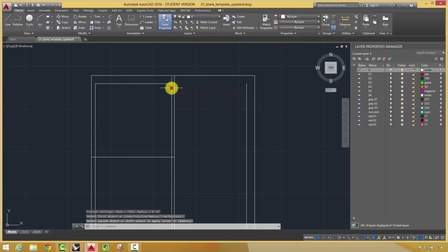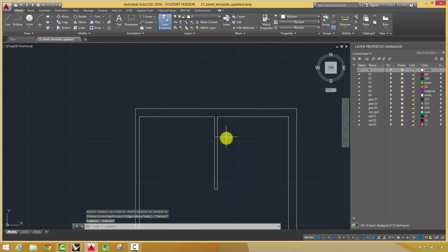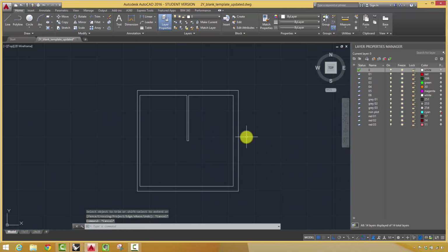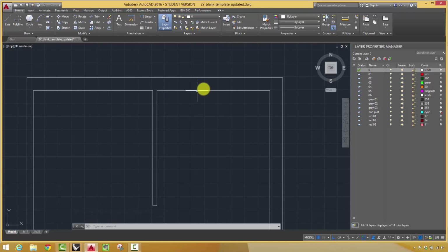actually, see, fillet doesn't always work because now I lose my line there. That's the way fillet works. So I actually do need to trim these. And once you get practice with trimming, that'll help. So you can see that the partition is not separated from the wall. The space, the wall, the thickness of it just kind of flows into it, right? There is not a line here.